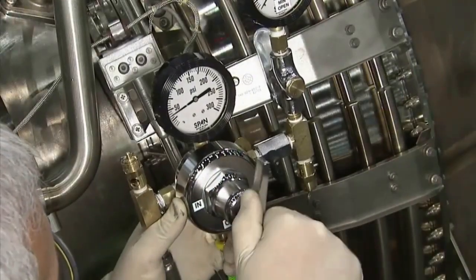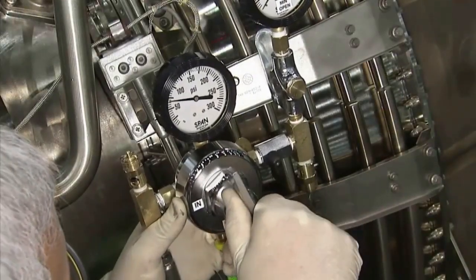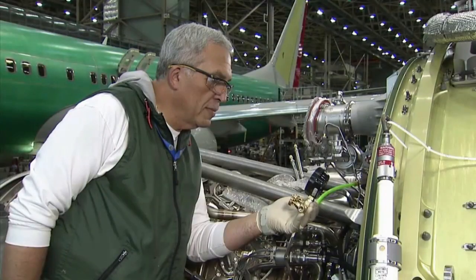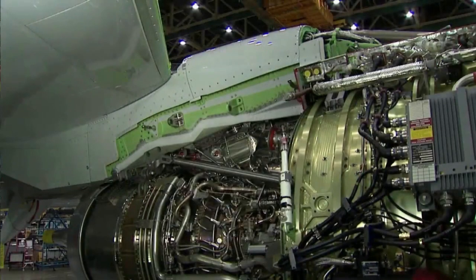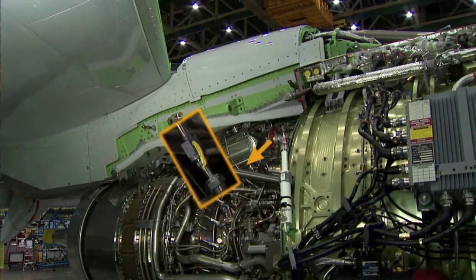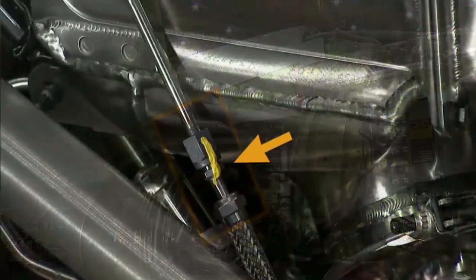Then reapply supply pressure. If the pressure on the PCCB test gauge is low, this may indicate a leak or faulty part. To eliminate the 390 sensor as the source of the leak, disconnect its control pressure line up near the right side of the pre-cooler and cap it.